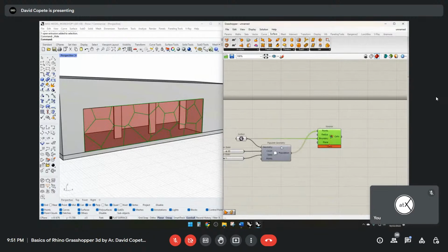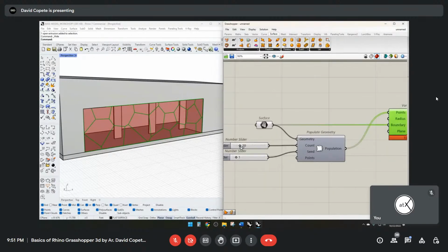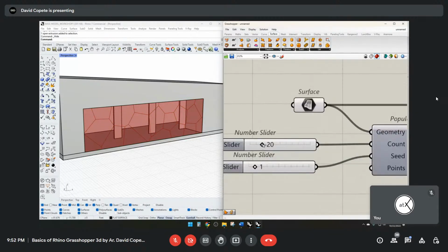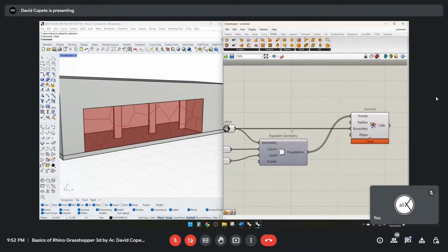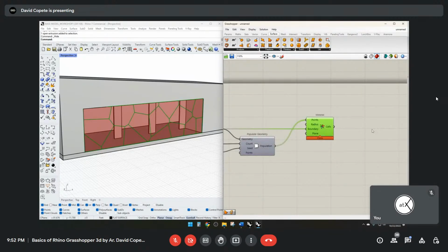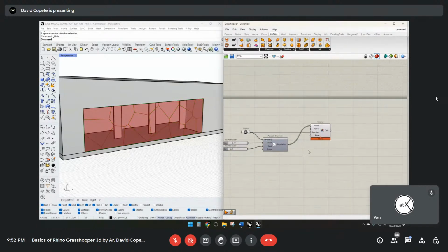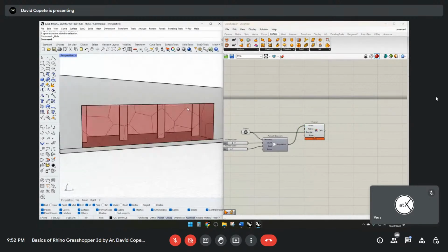And that's the other thing is you don't want to add too many points to then do some actions later on. I would rather you simplify your geometry and then work forward that way, knowing that maybe later you can increase it and not crash your computer, because this calculates multiple actions at once, and you probably had those issues before. So with this, now let's make this structural or something that we can use here.